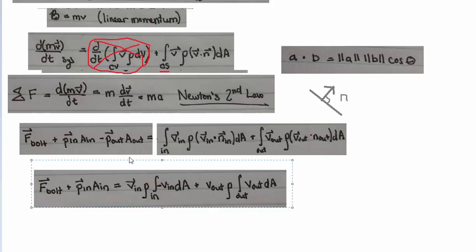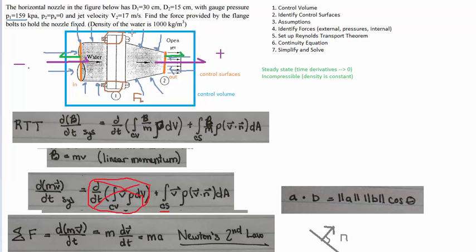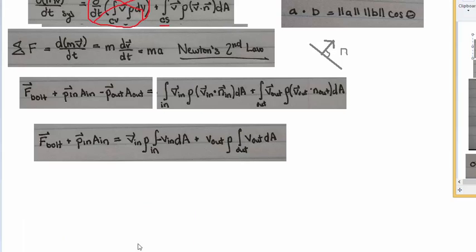Okay. Over here, there's no real changes. We just eliminated the second term because, remember, we were told from the problem statement that the second pressure is 0, because we're using a gauge pressure definition. So this magnitude and this magnitude are also scalars, so they're constants, and they can be pulled out of the integrand. What that means is that you simply have the integral over the area of dA, which is simply going to be the area.